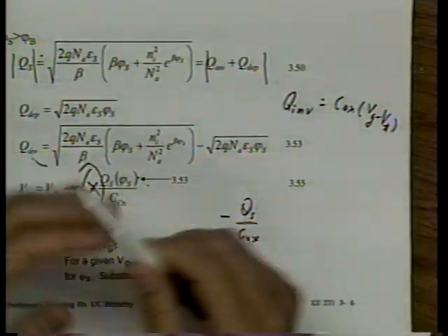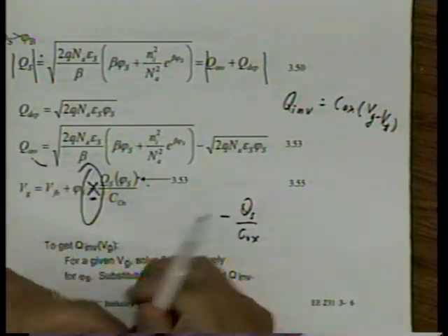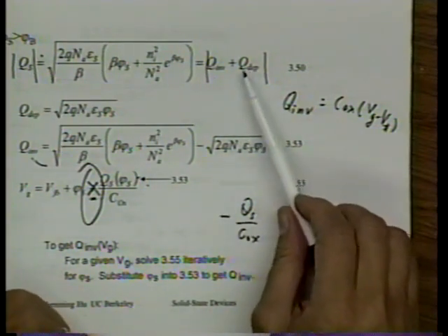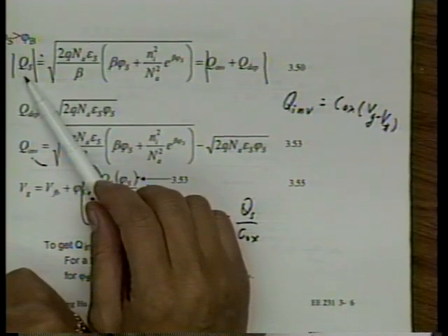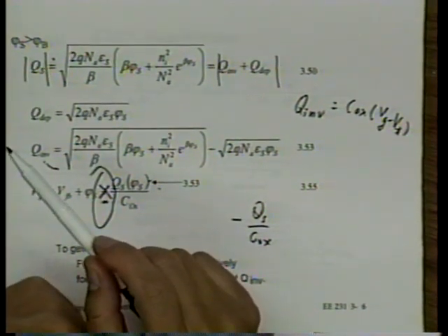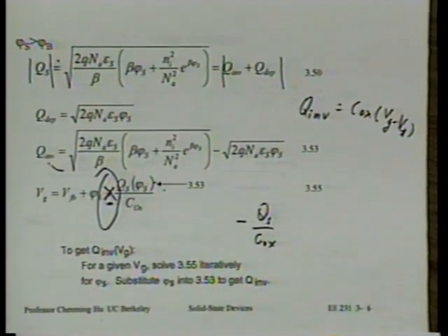So we're not forcing any charge to be positive or negative. So all charge can be either positive or negative depending on doping type, depending on the bias, whether we're in accumulation or inversion. All right? Okay. With that definition of QS, there should be a minus sign in front of the QS. Okay? Thanks. So I guess the only way to fix that is this.